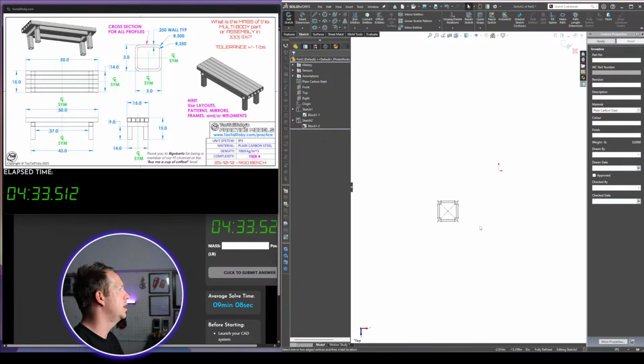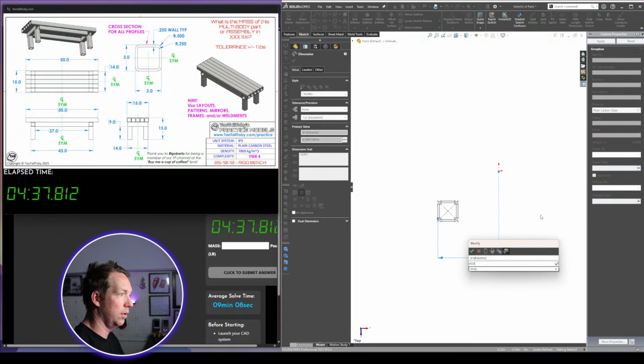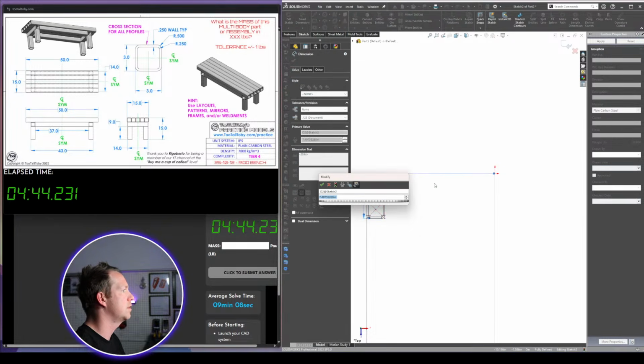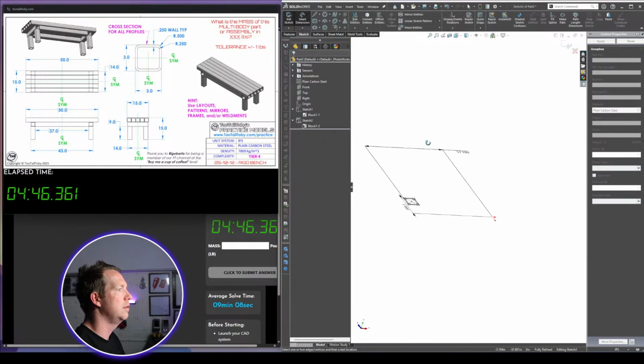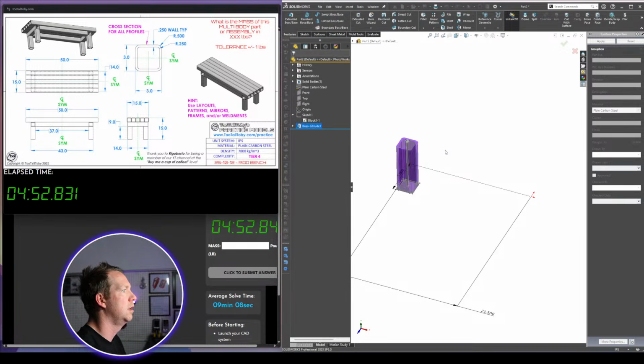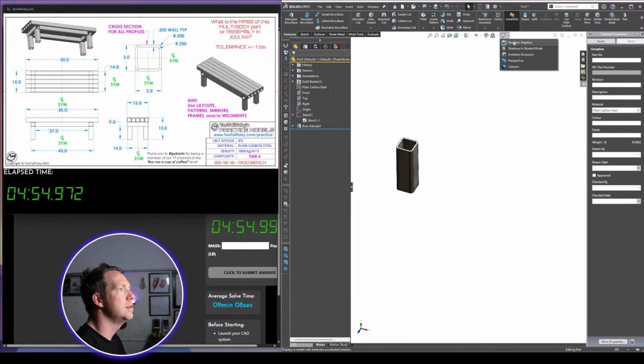And if I want to dimension it, I can then just use the dimension tool, and 43 by 2, I can find the location that it needs to be. So I can fully define that. So it's going to be 7. Alright? And then you can use a block like you would anything else. So I can extrude this one up 9. And that one is then done.